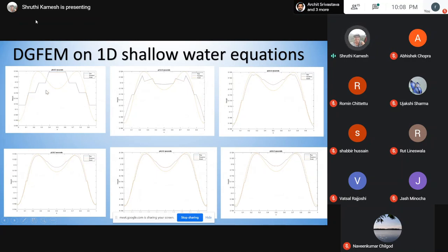And this is expected of finite volume, right? Each element has only one value to explain how it varies across each element. And you can see the discontinuities over there. This is at P0. Which means that if I had a finite volume solution using just 8 elements, I would not have a very pretty looking picture.